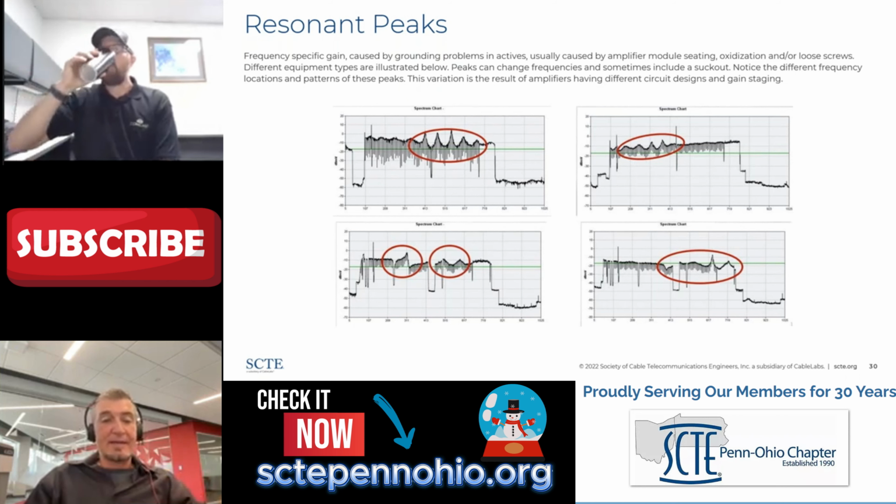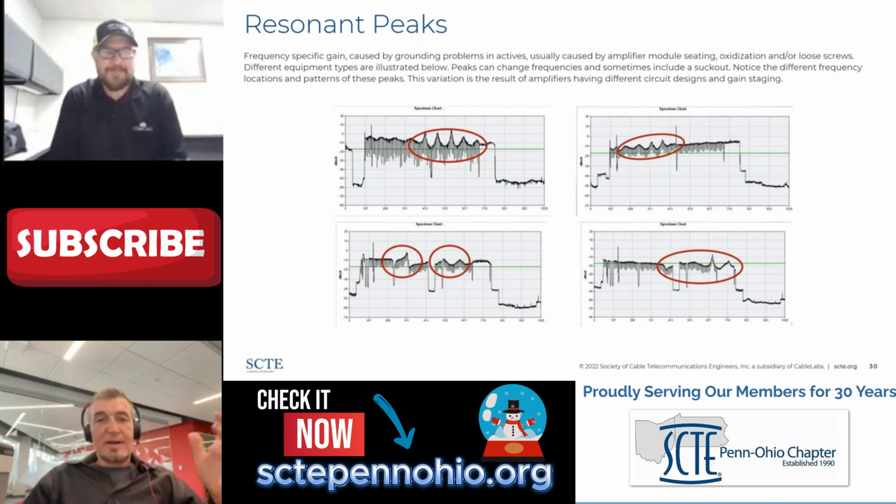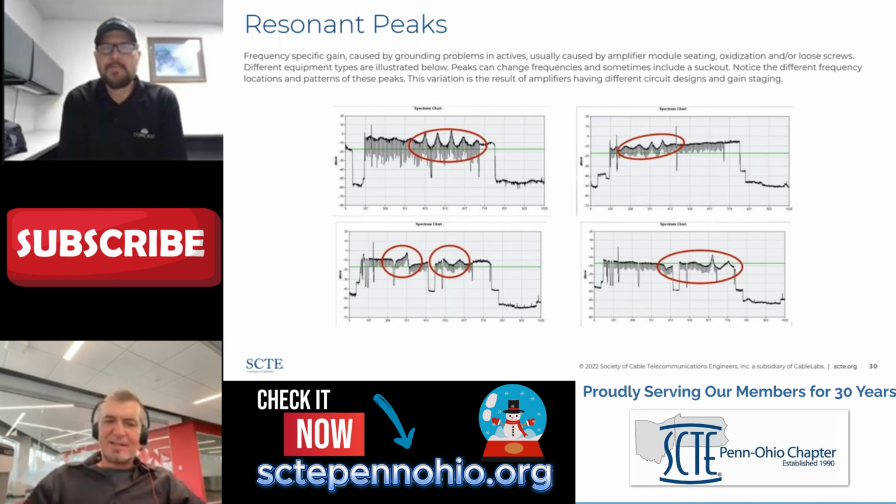I'm not here to pick on names and types, but I can tell you each one of these is a specific manufacturer and generation of amplifier and gain stage design. That's what determines where the peak is, and the magnitude is how bad the corrosion or whatever is, but the shape and the location is all about which manufacturer it is. And the one in the lower left-hand corner, you may say, that doesn't look like the rest of them. Well, it doesn't, but it is a resonant peak. It's just caused by a different gain stage design.